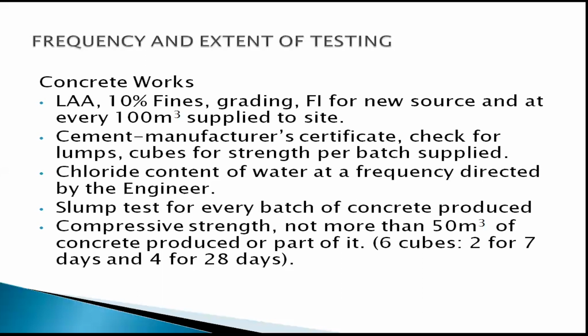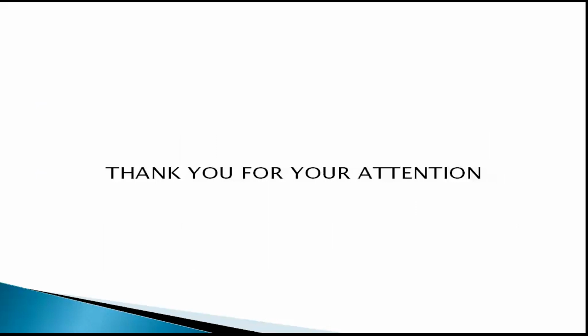Compressive strength of the concrete should be determined for not more than 50 meter cube of concrete produced or part of it. And 6 cubes, the minimum, should be prepared, and 2 of the cubes tested on the 7th day, and then 4 on the 28th day.